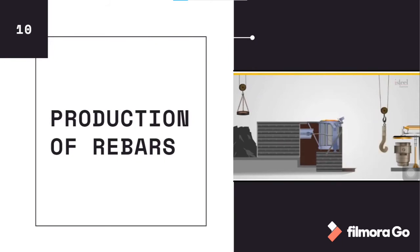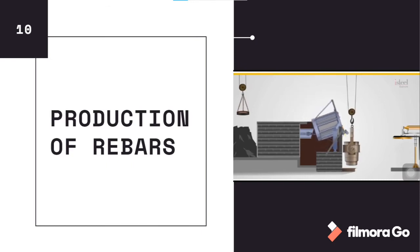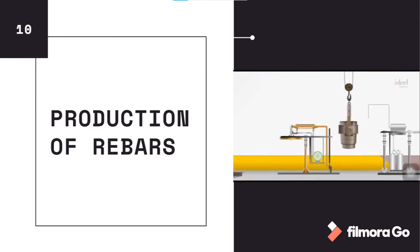When the liquid steel attains 1660 degrees centigrade, it is poured into a huge refractory-lined metal container called the ladle. The liquid steel is then purged with an inert gas to homogenize the temperature and to release any dissolved gases in the metal.